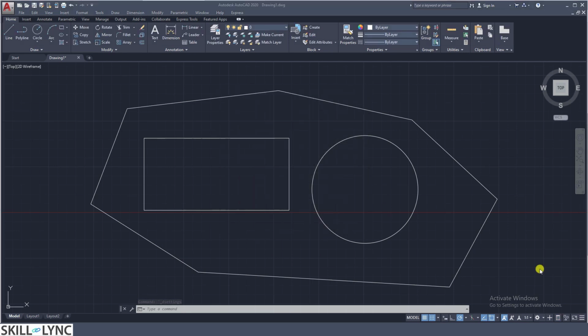So now let's look into the dynamic input modes. In the first week we had seen, during the construction of lines, the polar coordinate system and relative coordinate systems. We were using different commands to specify the dimensions or inputting the values on the screen itself. The other way was doing it on the command screen. So let us do a graphical inputting. It's called dynamic input. To enable that, you have to turn on the dynamic input mode.